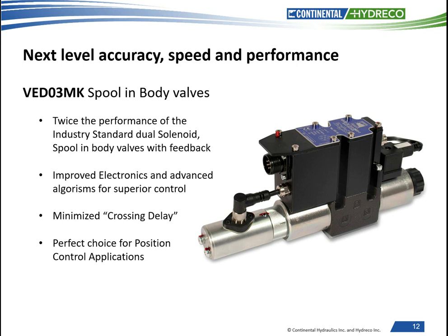So for high performance applications, they must jump to the next level, which is a spool and sleeve type design or a high-end servo valve to meet these requirements. Yes, we can do that as well. But before we take that jump, let's take a small step here. Continental also offers a very unique option, the VED03 K series valve. This is still a spool and body design, making it very economical and can still provide the high response. Thanks to improved electronics and advanced algorithms, the response of the K valve is rated up to about 100 Hertz operation.